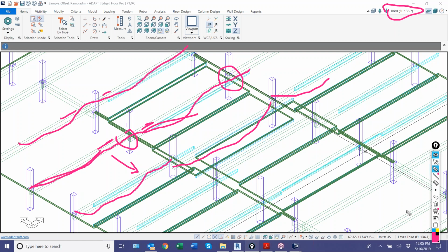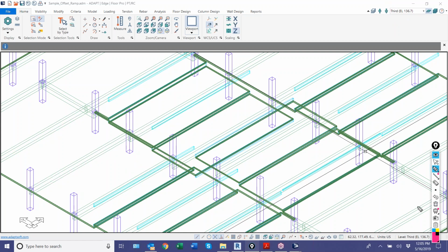We're going to back up now and talk about, okay, maybe we just want to assume that the ramps are flat. We're going to discontinue the ramp, or let's say disconnect the ramp slab from the parking slab by adding an opening, maybe along the joint. And we'll take a look now at that type of scenario.